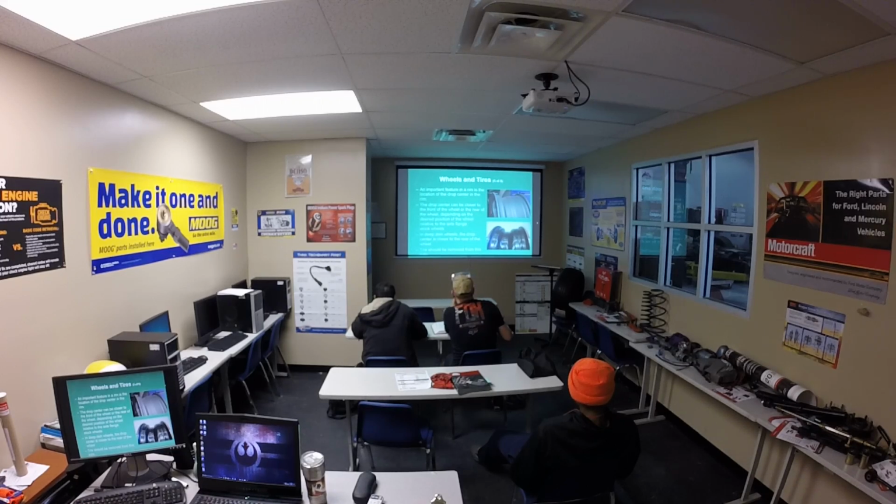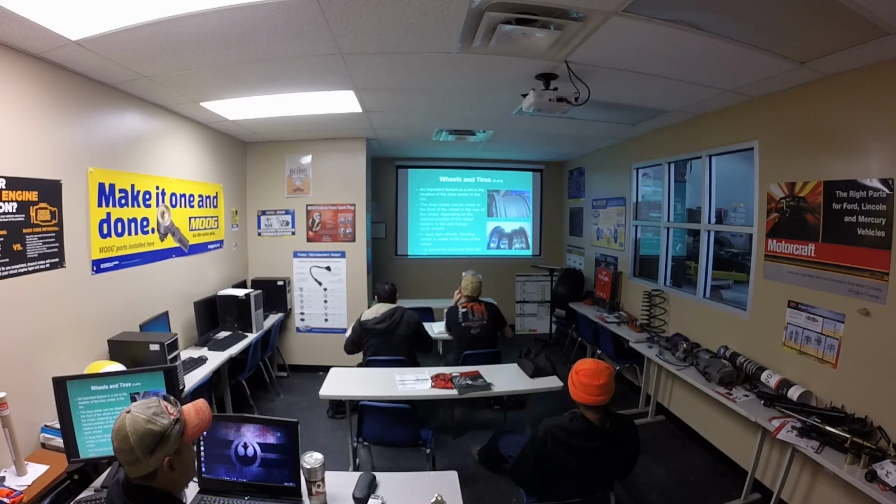In this top picture right up here, here's the front of the wheel. This part right here is called the drop zone. So this is a normal dismount and mount rim. This one right here, I believe it's also forward. This might be the front. All right, so if this is the front of the rim, this is a forward remove. When you remove the tire, this is going to be in the upright position, facing up. If this drop zone right here is all the way towards the rear, this is called a reverse mount rim. That means you need to remove the tire upside down.